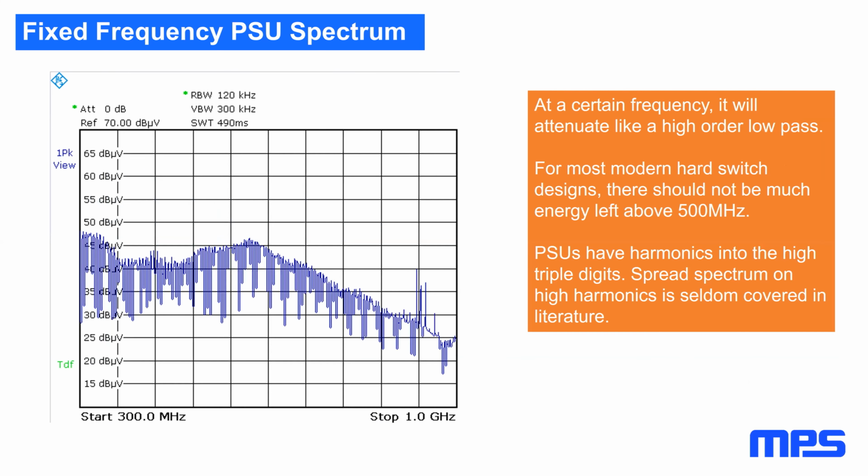If you go higher, you will see at a certain point, as with everything in physics, energy is not infinite, which means there is a crossover point here in the range of 400 or 500 megahertz, where the energy actually goes down. Here, these spurs are actually a GSM base station where my shielding wasn't perfect, so forget about this one. But here you can see that for higher frequencies above 500 megahertz, the energy goes down, and that's some free nice thing physics provides you.